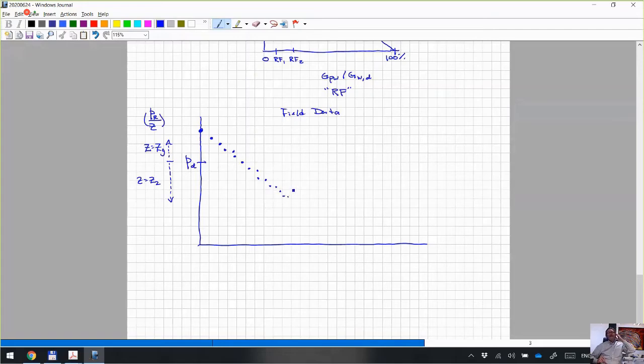Of course, Dake once had a luncheon lecture. What was the title of that? Something like why never to use the gas material balance, or the death of the gas material balance. His argument was that you never see real data that follows this. That's not true, because some of the really big gas reservoirs, high perm single reservoir flow unit like the Hewett, first UK big, follow just like this. But there are many that don't.